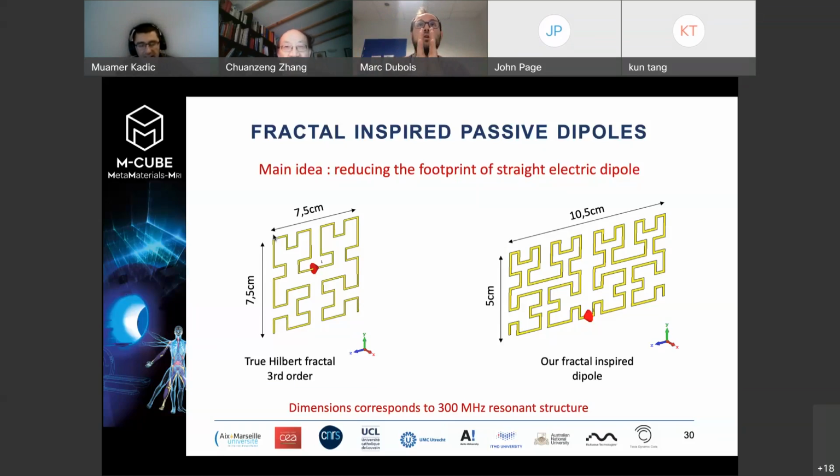Really, the pulse we are sending, the MRI pulse, they are something like, let's say 500 microsecond, 100 microsecond long, but the frequency is 300 megahertz. So you have 1,000 periods inside your pulse. So we still call it pulse, but it's almost like continuous wave excitation, in fact.